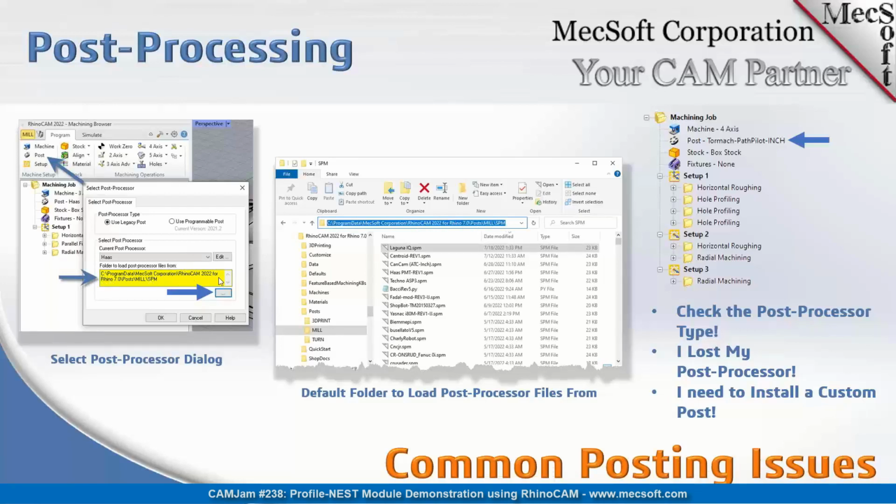That's the same folder path over here in this dialog on the left. And you'll see in this graphic a number of post processors already listed here. The posts by default have a file extension of .spm for our legacy posts, and .py for the programmable post. And then over here on the right, obviously we see a machining job with an example post defined.